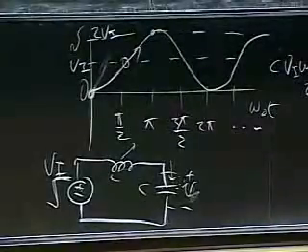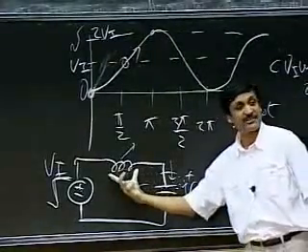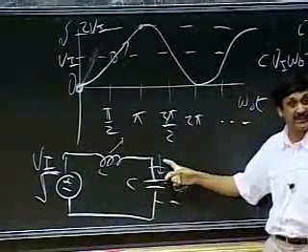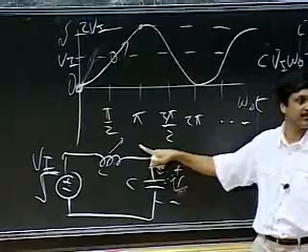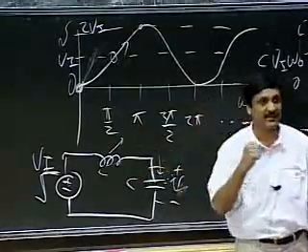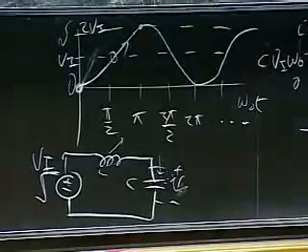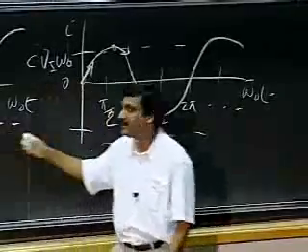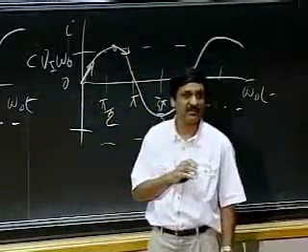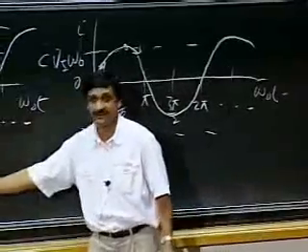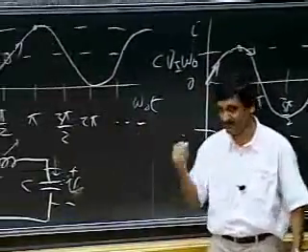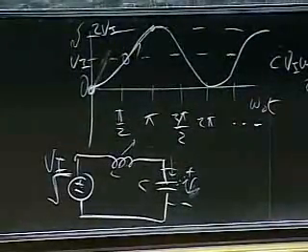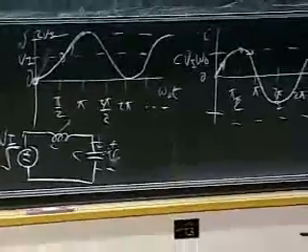This is a subtle insight which is absolutely spectacular. That with 0 volts across it, it still keeps pumping that current. Capacitor voltage has gone up, and guess what? The voltage on this side is higher now. But this guy is still pumping a current. Man, I've been born to do this, you know. I shall pump a current. However, because the voltage has now gone up here, gradually the current begins to diminish. But as far as the capacitor is concerned, you pump a current into me, my voltage goes up. At some point, like a runaway train, it comes to a halt.